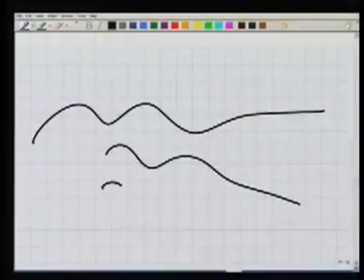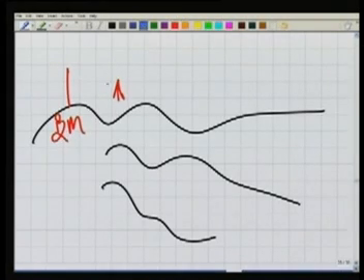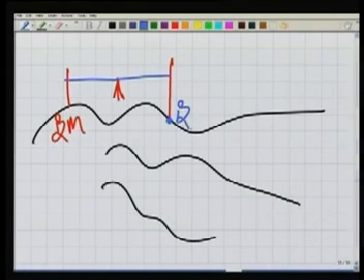For example, if we have a big area, I keep my level here, I know this is my benchmark. Benchmark means I know the RL of this point, and I take a backsight. We'll talk about this backsight and these sights again later on. I take a sight, then I shift my staff somewhere. Let's say this is the staff, and I take again one more sight. By doing this, I know the RL of this point P. Benchmark was A. Similarly, if there is a point C, I want to determine the RL of C, I will take